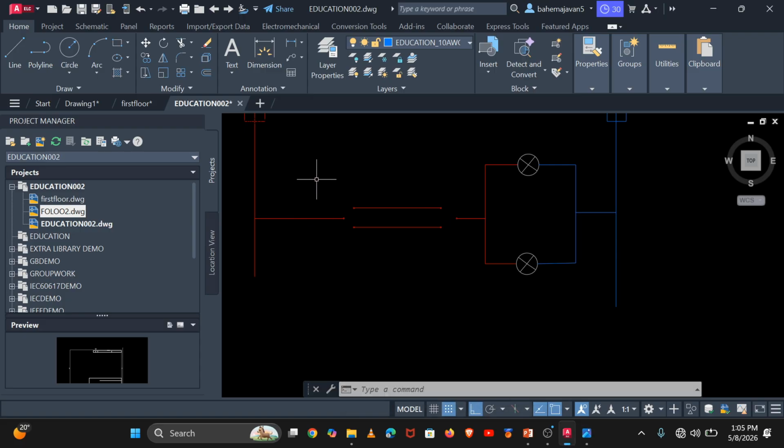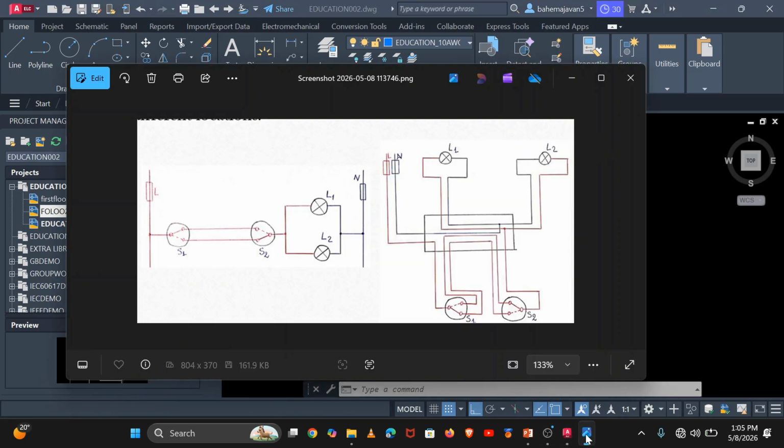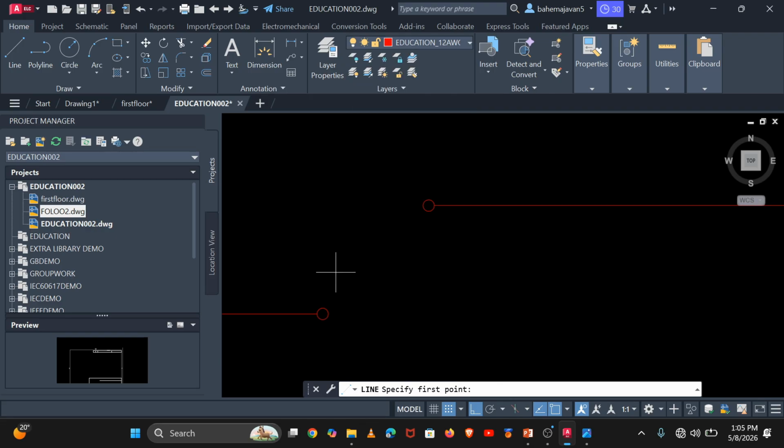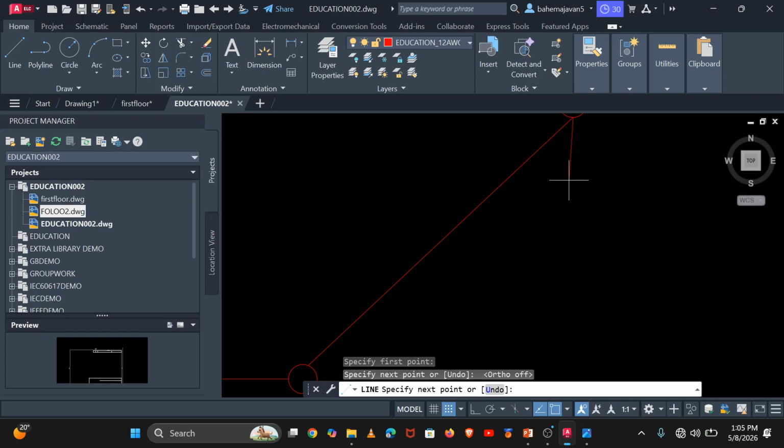And again, if you want to show this kind of dashed line, I'm going to show you the way to do it. Let us first connect these wires well, and choose line, snapping at some point, and we turn off the grid there, and we do it like this.